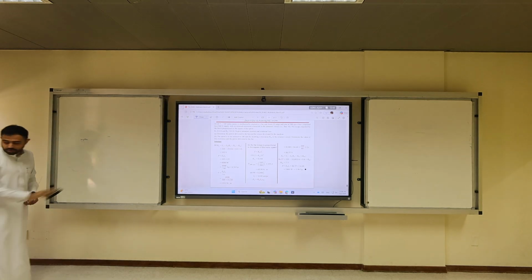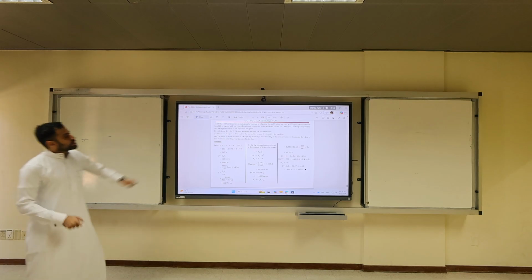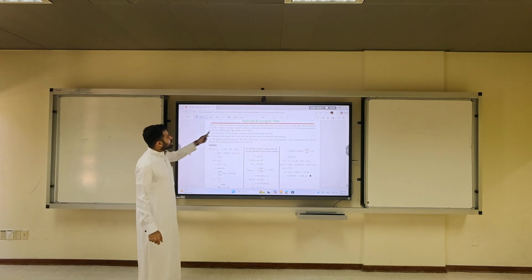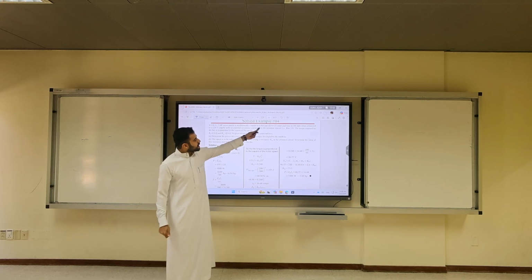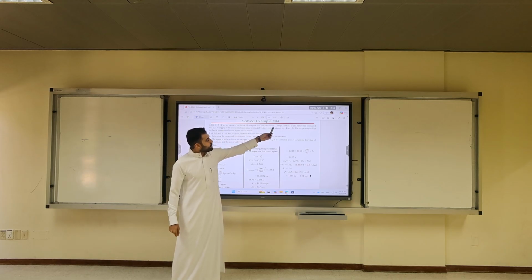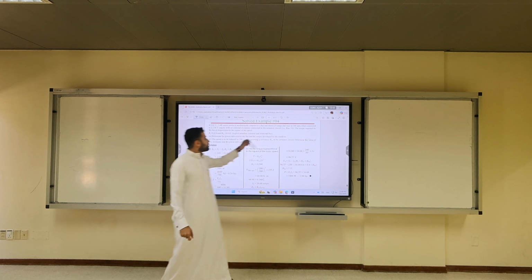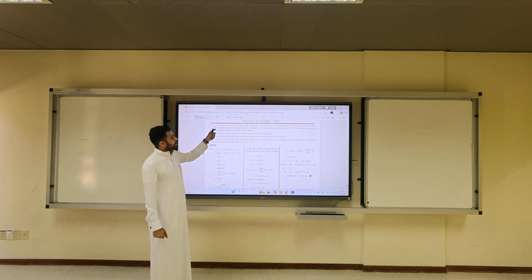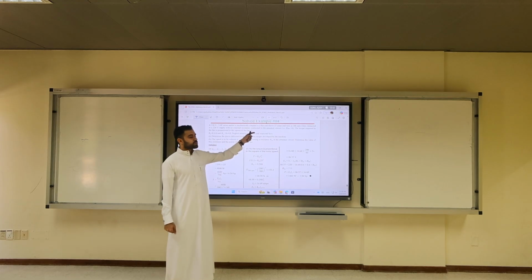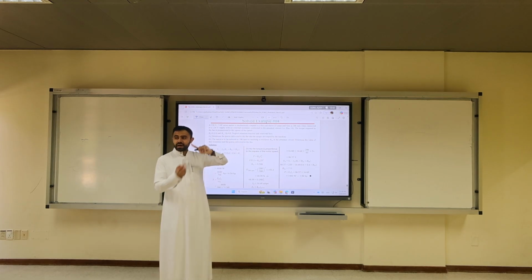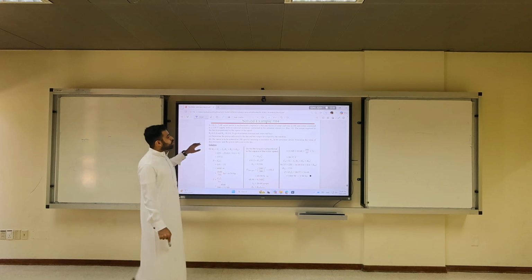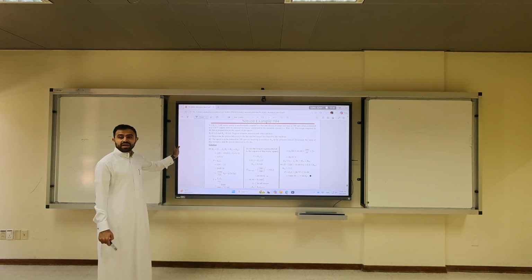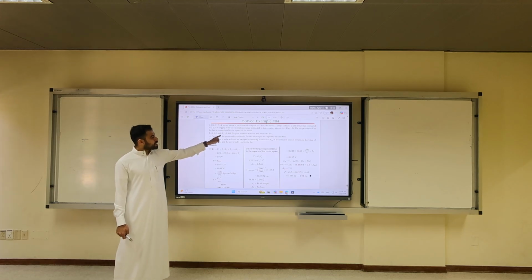Here we're going to have more control. A 220 volt, 7 horsepower series motor is mechanically coupled to a fan and draws 25 amps, runs at 300 RPM when connected to 220 supply. There is no external resistance connected, so the only series resistances are RA and RF. The torque required is proportional to the square of the speed because it's a fan. RA is 0.6, RSR 0.4.